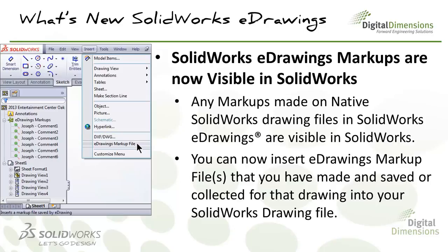Now in SolidWorks 2012 eDrawings and prior, in order to utilize these eDrawing markups, you had to open eDrawings viewer and your SolidWorks drawing file side by side, and then you could read the markups and then make the appropriate changes in the SolidWorks drawing file.